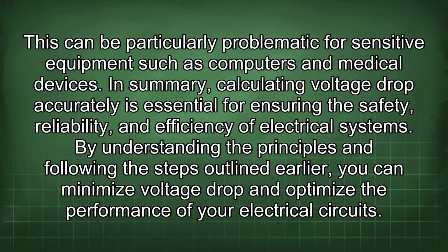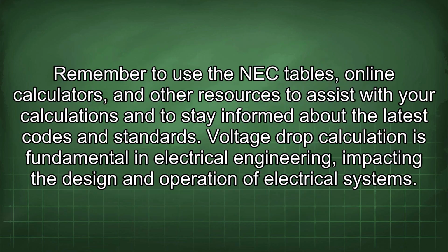In summary, calculating voltage drop accurately is essential for ensuring the safety, reliability, and efficiency of electrical systems. By understanding the principles and following the steps outlined earlier, you can minimize voltage drop and optimize the performance of your electrical circuits. Remember to use the NEC tables, online calculators, and other resources to assist with your calculations and to stay informed about the latest codes and standards.